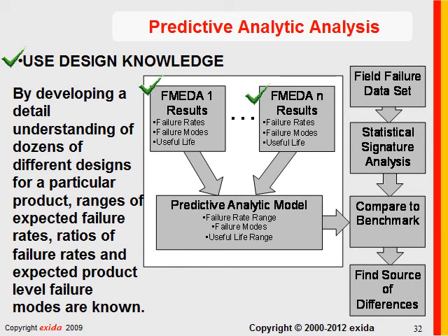Question is, if you have been proof testing every 12 months and collecting data suggesting proof testing could be extended to 2 years, should this change be done in steps? Is there a calculation to work out the step increments made? That's a good question. The bottom line is, based on mathematics, you could make the change to the new value.